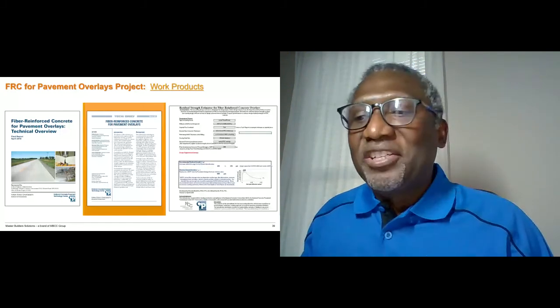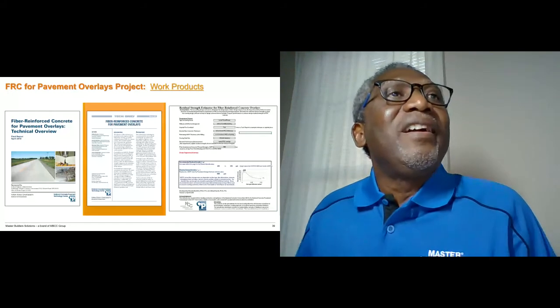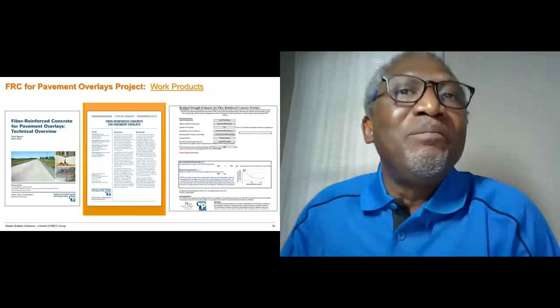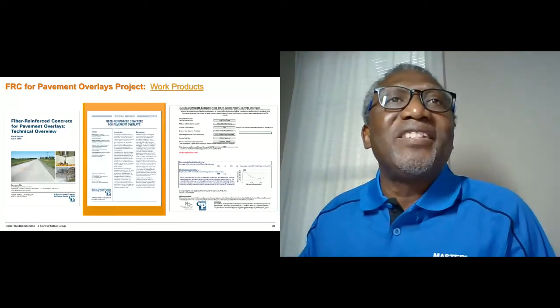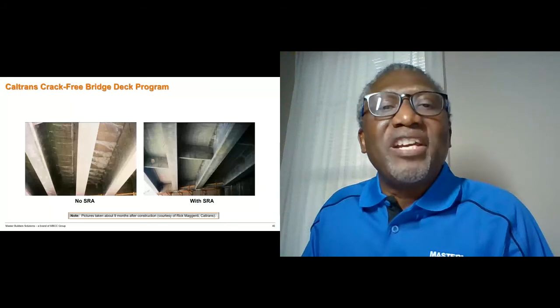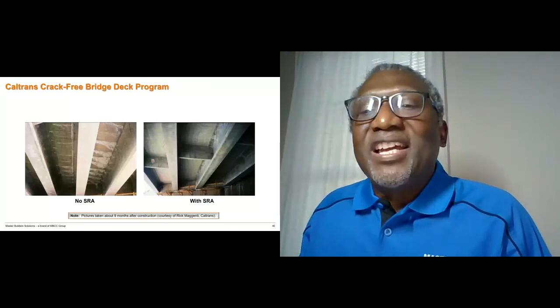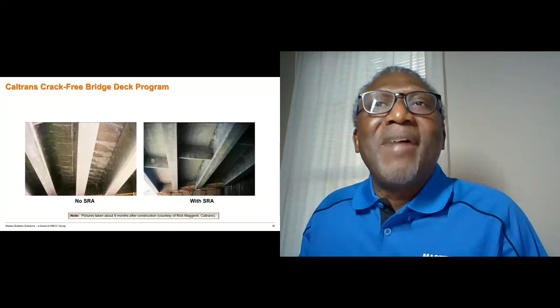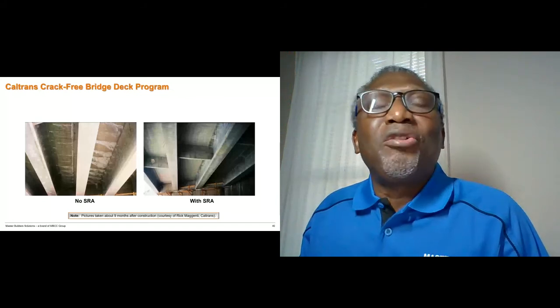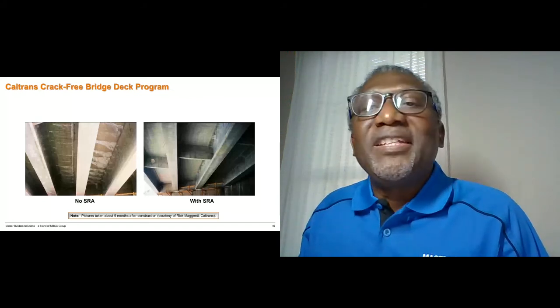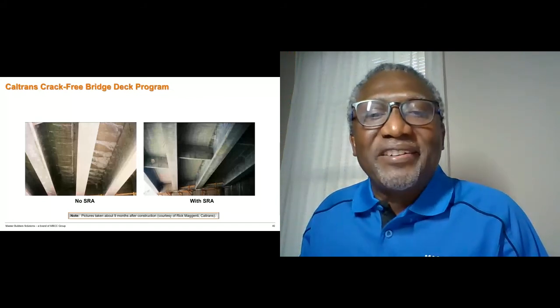And talking about bridge decks, just real quickly, Caltrans did a study back in 2002 where they looked at using shrinkage reducing admixtures in the bridge deck. And after 9 months, they saw a marked difference in cracking between the treated and the untreated sections.